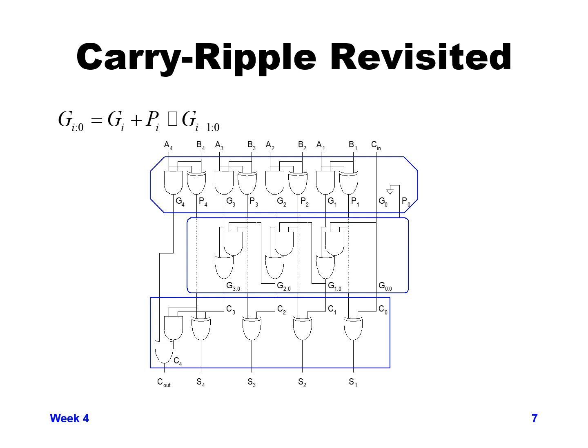So this is what I was talking about several foils ago, where for this particular type of function, every bit, the carry has to continually ripple through bit to bit to bit. You can see where your critical path is, this carry rippling through. Now it's just rippling through a smaller amount of logic because we've calculated the propagate and generate already, so we don't need to calculate A and A bar for each bit.